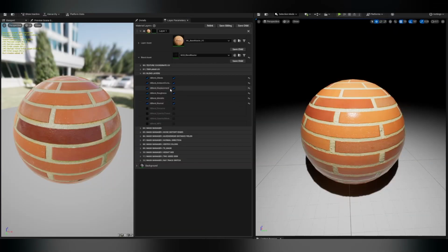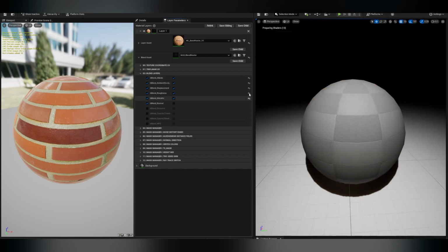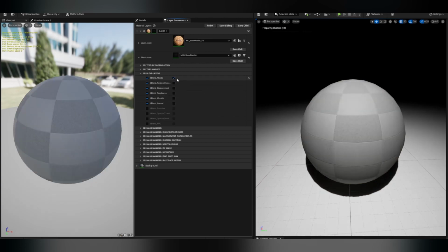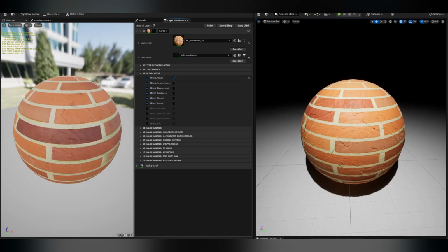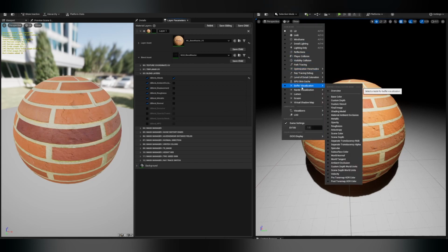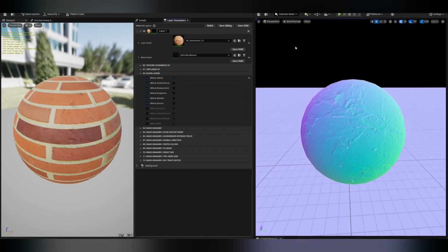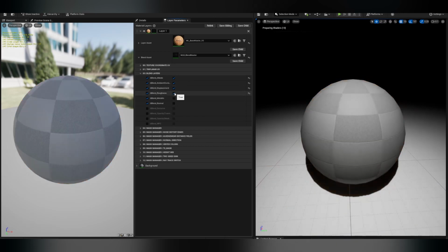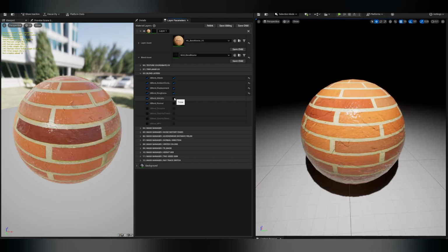Blend layers. In MLB Blend Master, you can blend various channels between top and bottom layers to achieve complex material effects. Settings such as B-Blend Albedo, B-Blend Ambient Occlusion, B-Blend Displacement, B-Blend Roughness, B-Blend Metallic, B-Blend Normal, B-Blend Emissive, and B-Blend Opacity allow you to control the blending of different material properties. Ensure to configure the appropriate blend settings based on your desired material outcome, and discard unused channels when possible to save on performance.